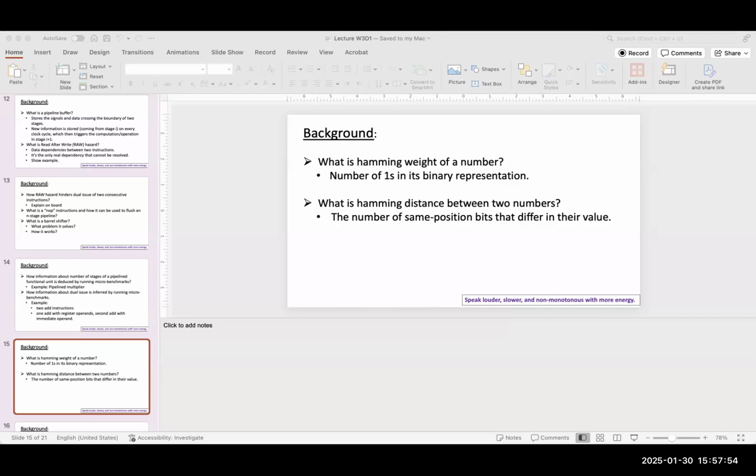Okay, so if you have read the paper in a structured way, you may have found that there are 2 main contributions. One is that they use the CPI indexing to figure out the hidden architectural details of the processor. And second, they do the power analysis to find out the architectural sources of information leakage. In doing that, they are not only doing the power analysis; they are saying the power profile they found reflects the Hamming distance and Hamming weights of the values stored in different registers or different architectural components of the processor at different times along the execution of the instructions or micro benchmarks.